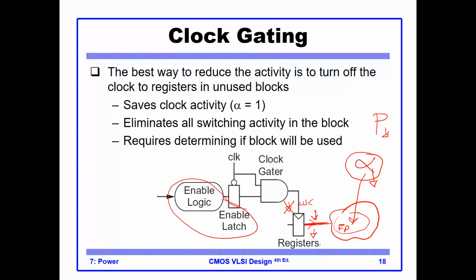And if this unit that you are trying to keep quiet is small and it is active most of the time, then probably creating such an overhead is not worth it. However, if this unit here is a large unit and it is not active most of the time, then creating this extra overhead probably would make sense, and you will overall reduce power.